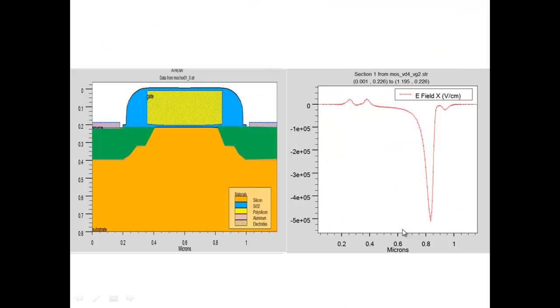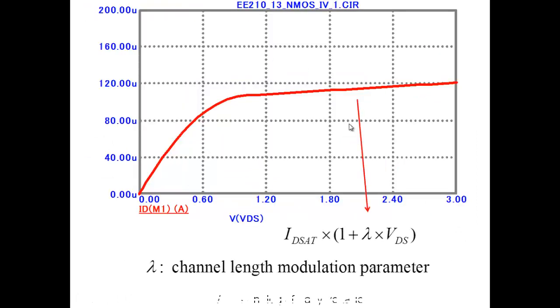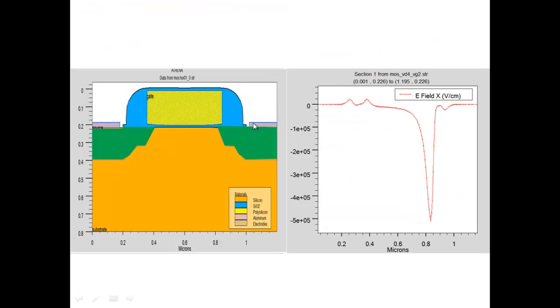All right, so I was telling that there is a high field region here. You can note, these are results from simulation, and you can see it is plotting the field as I go from here to here. So note what happens to the field here. Don't worry about the direction. As you reach this drain end, note how high the field goes.